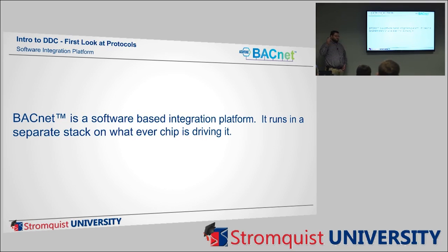And really, if you have that problem with BACnet, it's a lot easier to break those buses up into different segments. If you have one piece of equipment that doesn't follow all the rules of BACnet, because BACnet is an open protocol and people can write their own proprietary stuff and put it over a BACnet bus, you can separate that stuff a lot easier with BACnet.